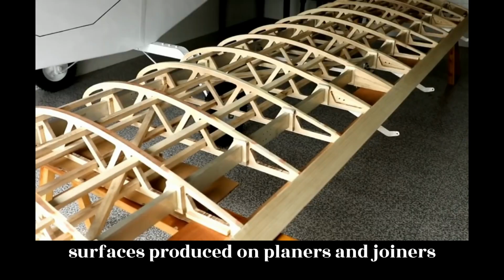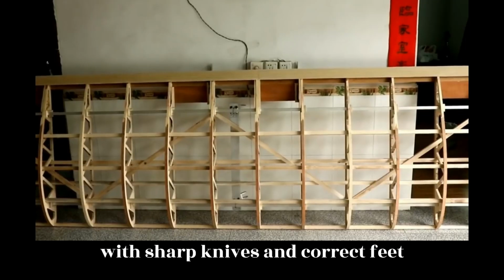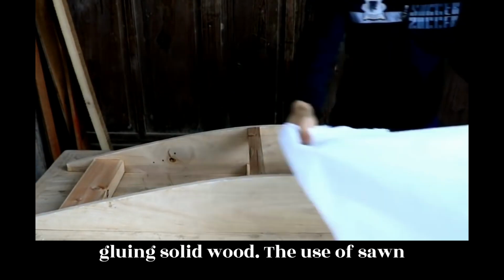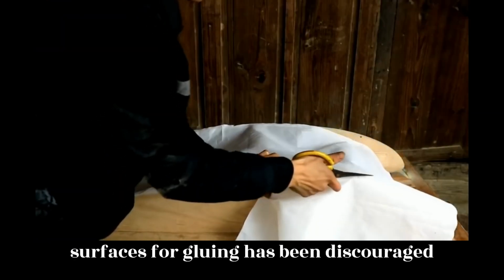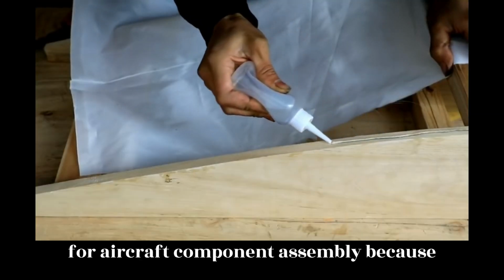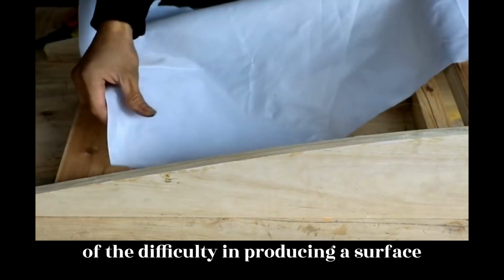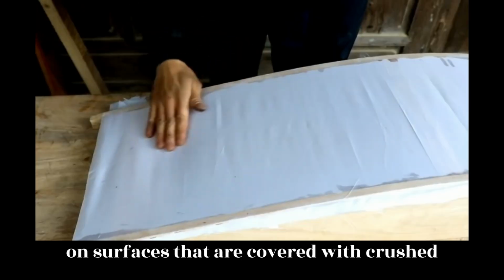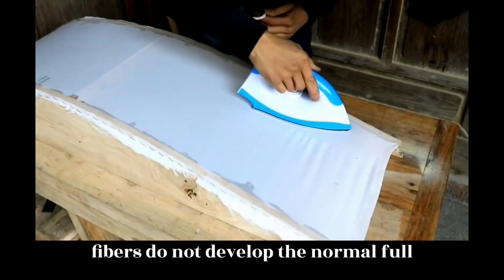Smooth, even surfaces produced on planers and joiners with sharp knives and correct feed adjustments are the best surfaces for gluing solid wood. The use of sawn surfaces for gluing has been discouraged for aircraft component assembly because of the difficulty in producing a surface free of crushed fibers.